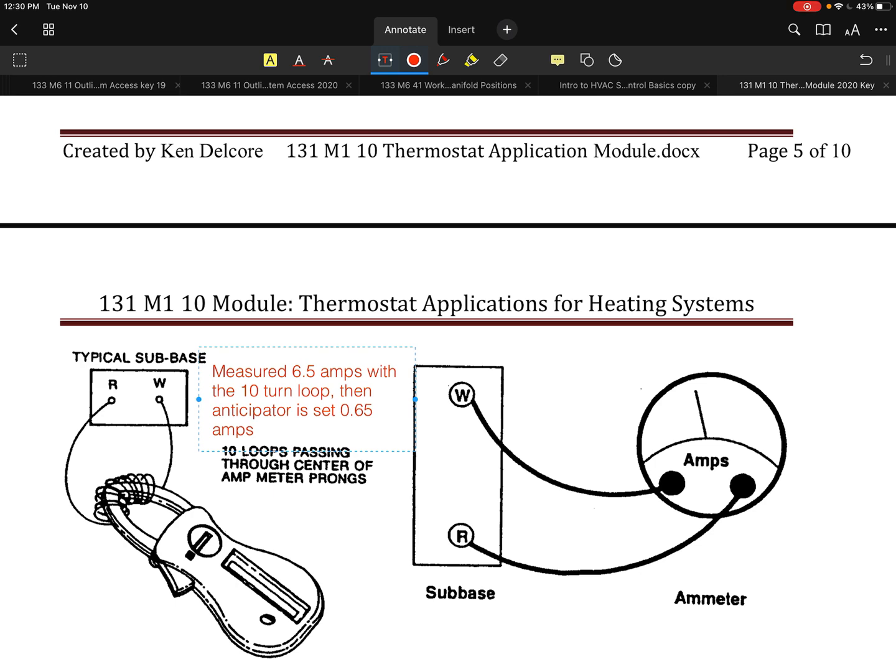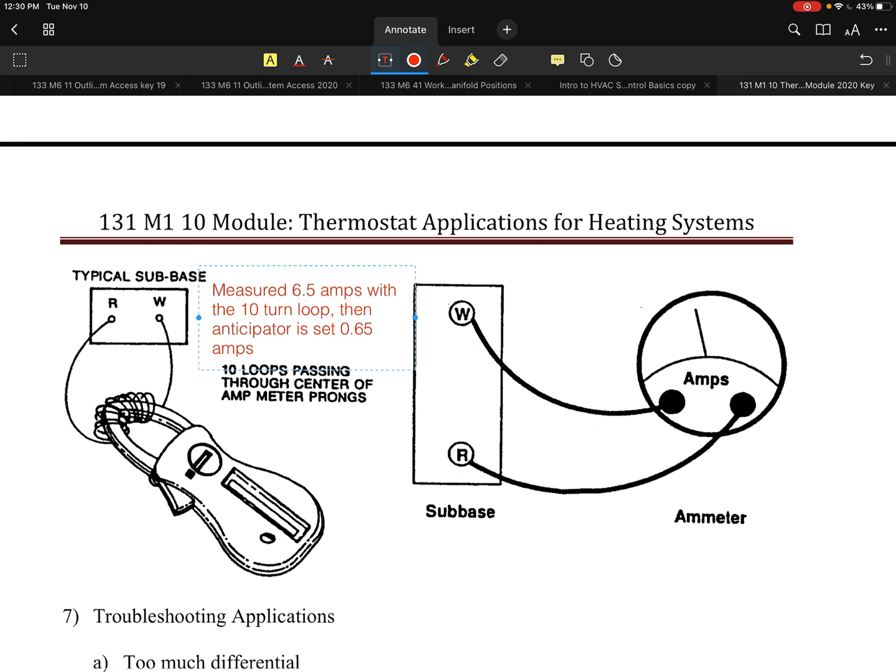That works well, especially when you have meters that don't always measure inline amps. The other way is if you have a digital multimeter. In most cases, you would have more accuracy by creating a multiplier loop and measuring that, and then dividing that out to make your adjustment.